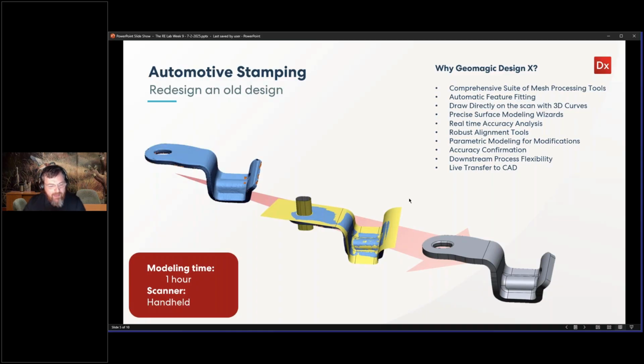Whenever a sheet metal or stamping application comes up, this is the way I usually steer people on how to reverse engineer it. The idea is that if we reverse engineer it as a constant thickness part, then you can load it into the CAD software you're working with, and they have sheet metal applications that will flatten it out, including all the bends, for you.